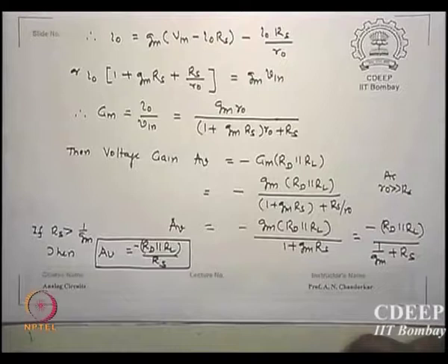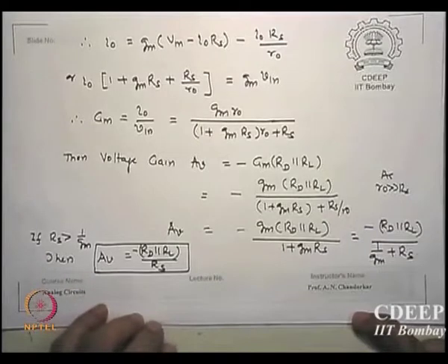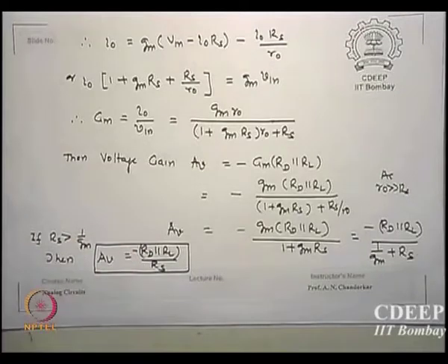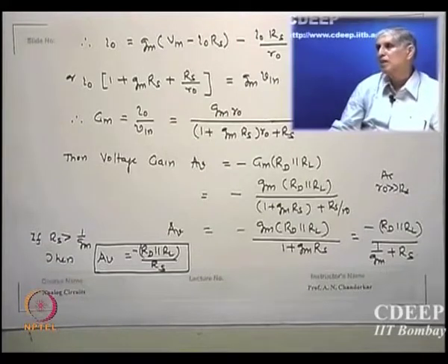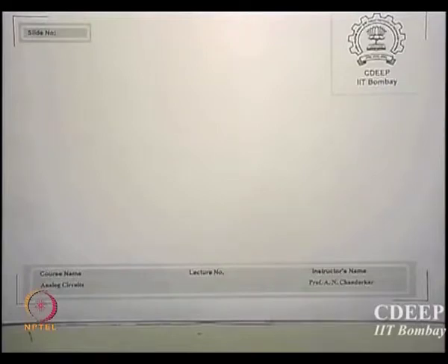So this is what we did last time. We calculated the gain function last time. The voltage gain is roughly equal to RD parallel RL by RS, and we said the advantage of this is that none of the numerator or denominator terms have device parameter dependence, no beta, no gm or whatever it is, and therefore no temperature dependence either, so it is a very stable amplifier at the cost of reduction of gain. This is why we still use these amplifiers.